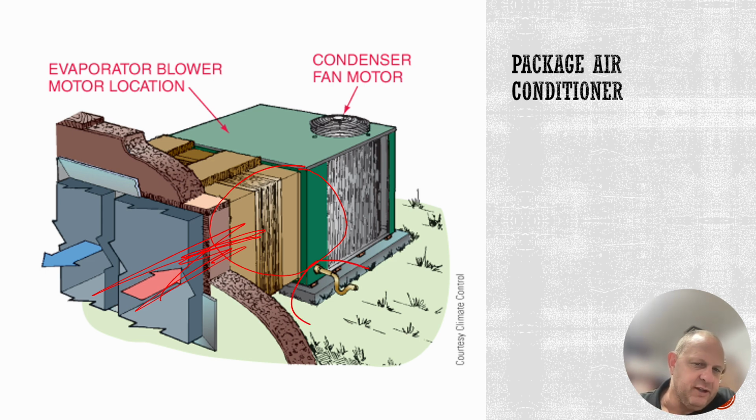And yes, we do need to trap that drain because air can get sucked up into that drain, causing the condensate water coming off the evaporator coil to back up into the unit and then to spill over into the occupants of the building, or the occupants of the factory, or wherever the rooftop unit's going to be installed.